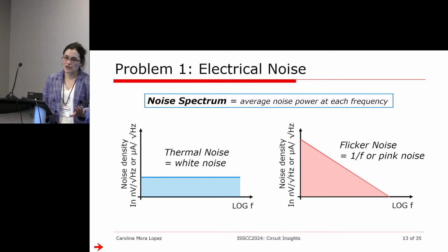These types of noise differ in their properties. What is important about flicker noise is that at lower frequencies it can be very high, while at high frequencies it is very small. For example, RF designers don't care about flicker noise anymore, since they work at very high frequencies. But for all low frequency applications, including biomedical circuits and also audio circuits, flicker noise is very important.